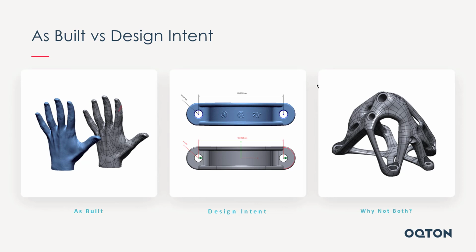The second option here is, with a mechanical part, if I 3D scan the shape and I measure between those holes, let's pretend the distance between those holes is supposed to be 3 inches. If you scan a part or measure with a CMM or a pair of calipers or anything, you can grab those calipers and make a measurement from hole to hole. It'll never be 3 inches, right? Because there are tolerances built into manufacturing.